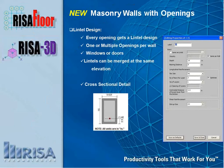We'll see exactly what the input of that looks like as we go into the program. But we also have here the picture of the cross-sectional detail. So it shows us exactly what we're looking at, a 16-inch block here with 3.5 inches, one number 6 bar from the bottom. So it's a really nice view of exactly what it looks like when we have that lintel designed.